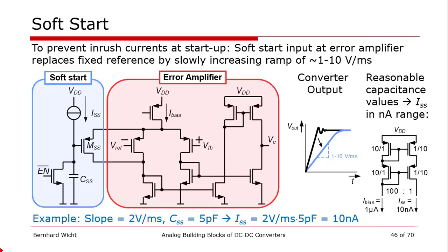One interesting aspect: if we start up our regulator, our output capacitor is fully discharged, and we would get a large inrush current. This little picture here indicates what we would see. Our output voltage would immediately jump up with the maximum speed, and we get even some ringing and a lot of stress. So we don't want to have that.